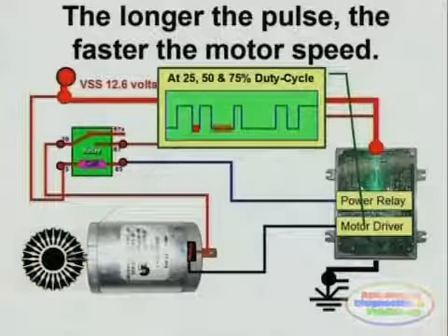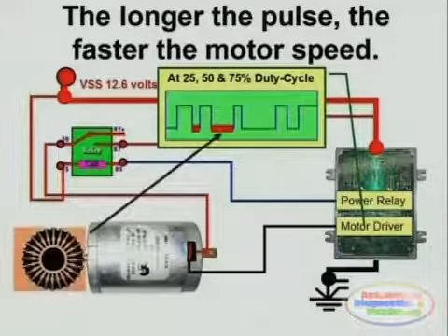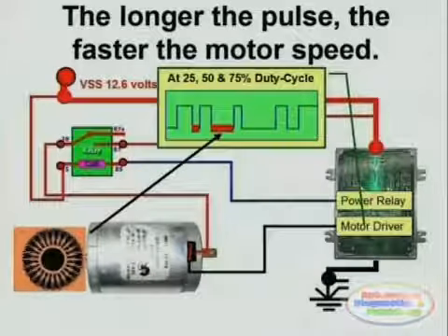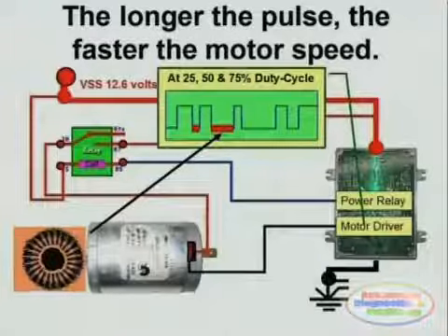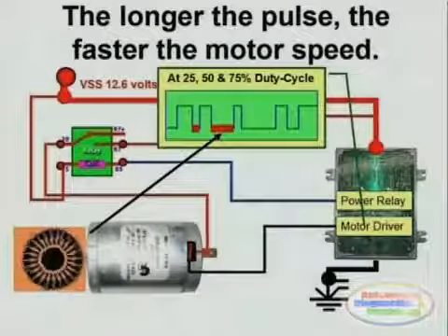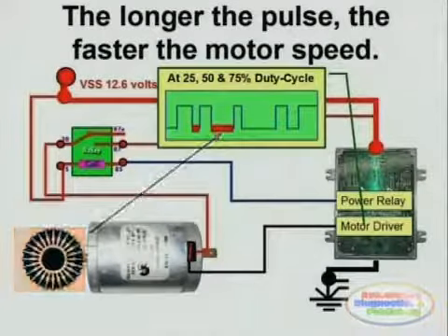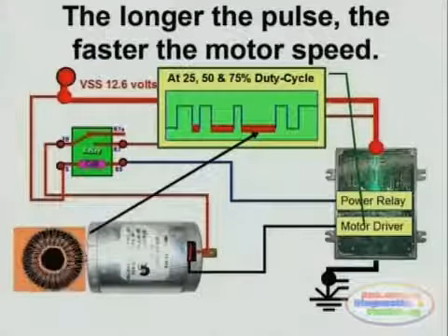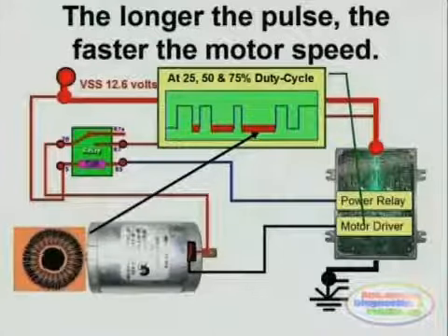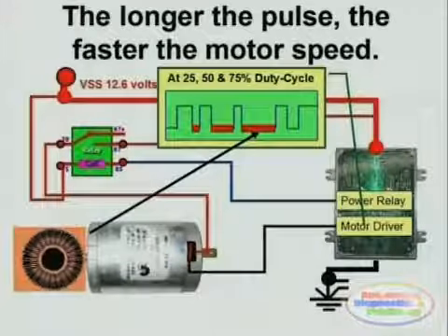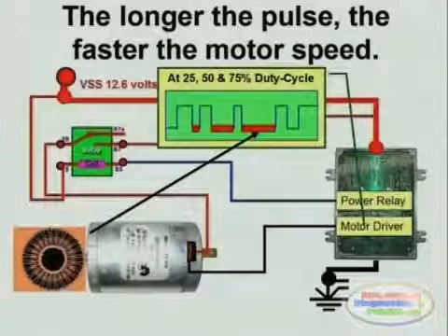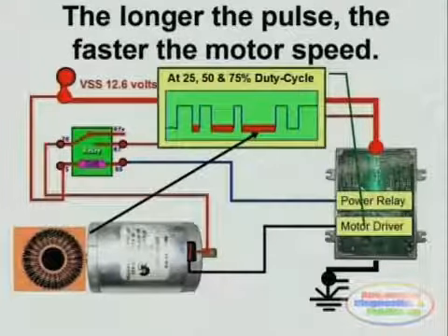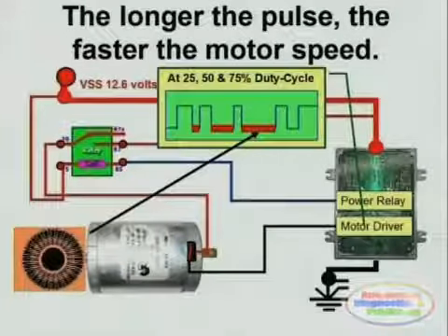At cruise speeds, for example, you will need maybe a 50 to 60% duty cycle for the fuel pump, and this we can see on the screen. And during extremely loaded conditions, as for example when towing, you will need maybe a 75 to 90% duty cycle, making the flow of fuel through the fuel rail a lot higher. You will need this type of arrangement in any system that is returnless.